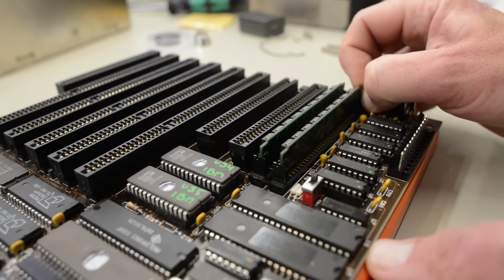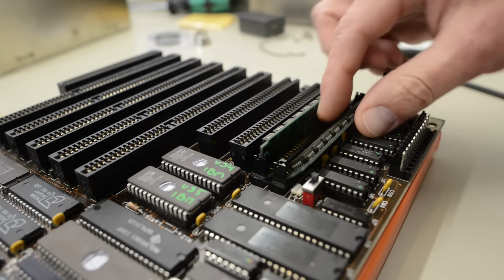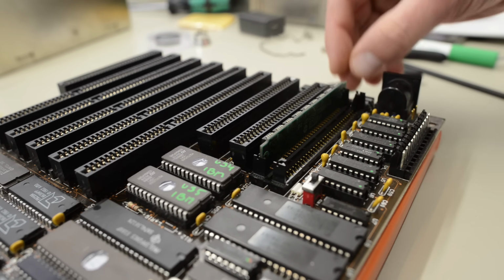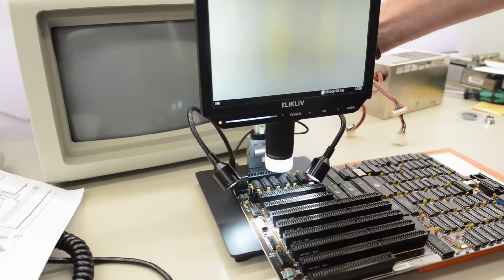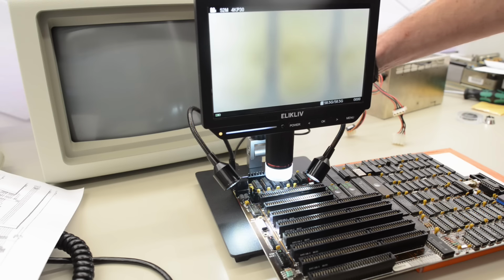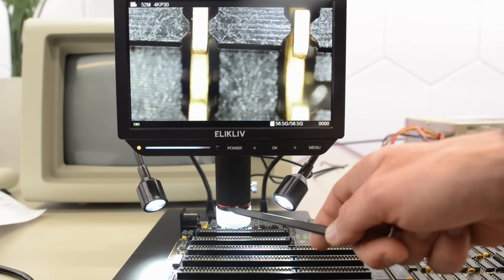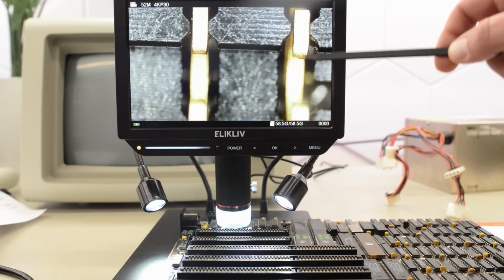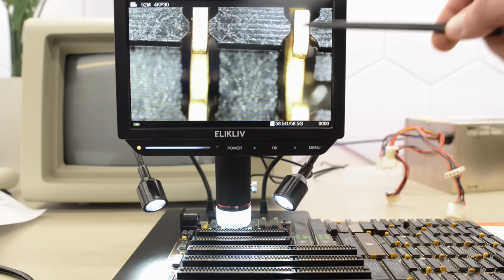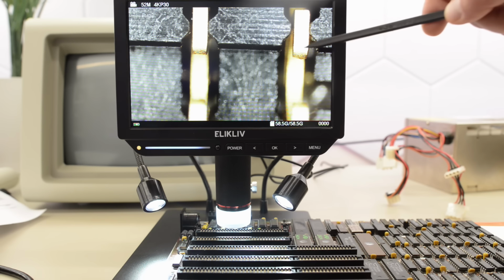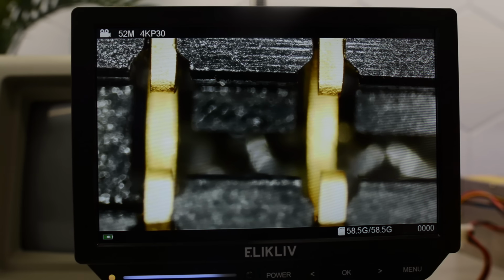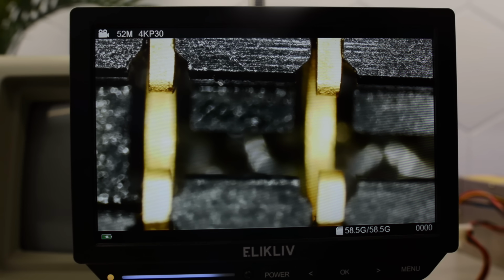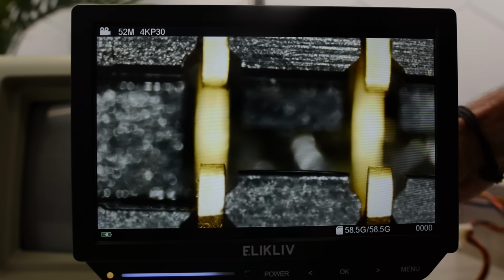Yeah, this type of slots aren't great. They have given me trouble more than once. Let's remove those SIMs and get the board under the microscope. So with the lens this close to the board, we are of course going to get a very shallow depth of field. But the interesting thing here are these tabs here. Well, my capture PC is still dead, so I'm going to have to record the screen. Not ideal, but this should be good enough so we can check these tabs and see if they are all okay. Those are good.